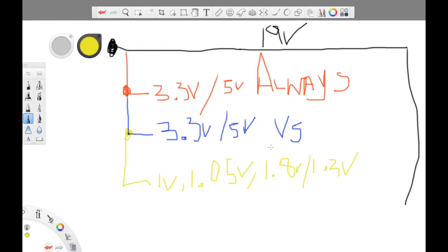Okay, you can't expect your CPU to turn on yet you are missing the 3.3 volts. Okay, that's what happens. All this power is distributed almost like this. I can't go deep into detail. I can, but I want to make this video as simple as possible so that you will learn, guys, and understand how laptop motherboards are fixed.